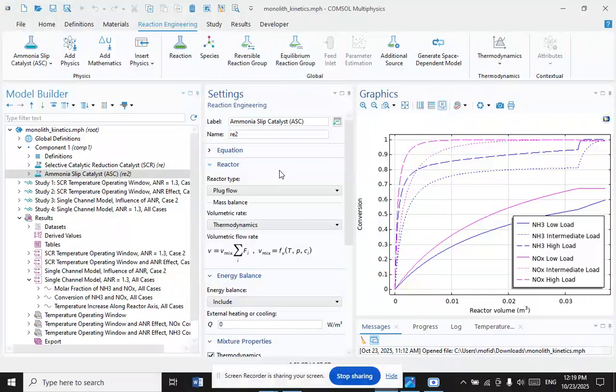The dosing rate of ammonia has a direct influence on the conversion of NOx. Too low dosing rate leads to exhaust of unconverted nitrogen oxides, while too much ammonia may give ammonia slip or even NOx emission, since a side reaction in the ammonia slip bed is formation of NOx from ammonia.